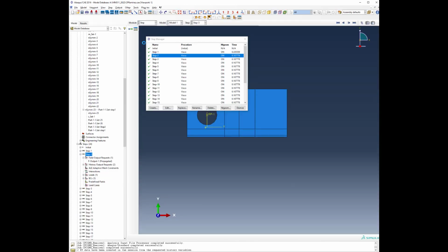if we look at step one, it was for 0.33559. So it went for 2 cycles, nothing happened there. Basically it just applied a load of 900 newtons, and there was no amplitude given, so it is applied instantaneously as that minor load. So that much time it took, so that is okay. And after that, in step 2, it took 1 cycle, so loading, unloading and holding of 600 seconds, and after that 1 node was released, or no, so 12 elements were released.